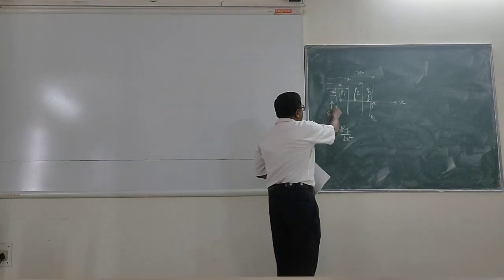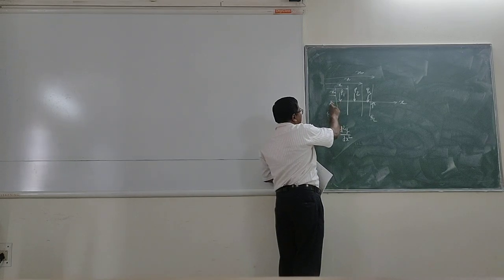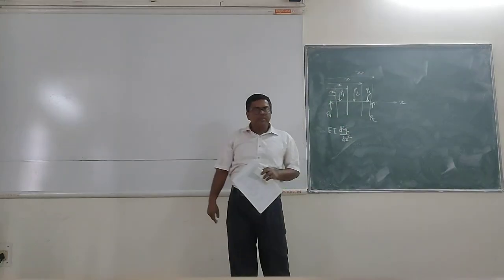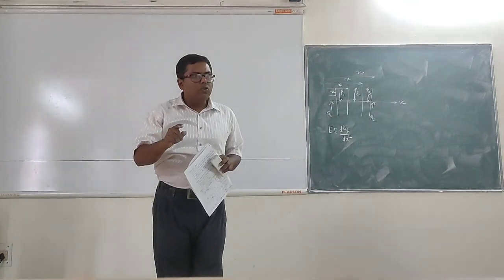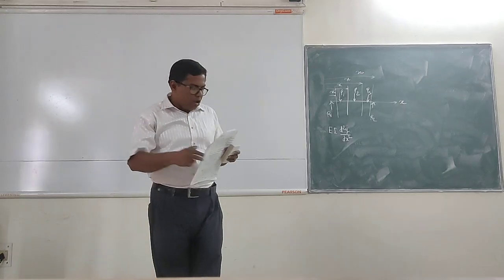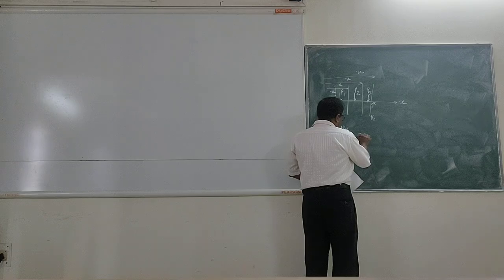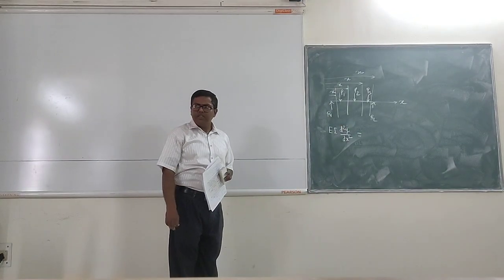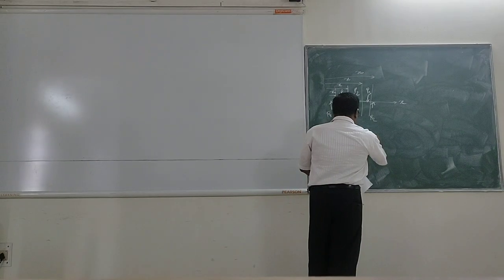Now if I take a section over here, what is the moment? d2y dx2 is equal to Mx, right? So if I write that Mx, what will be my moment? It will be R1 into x, right? So it will be R1 x.